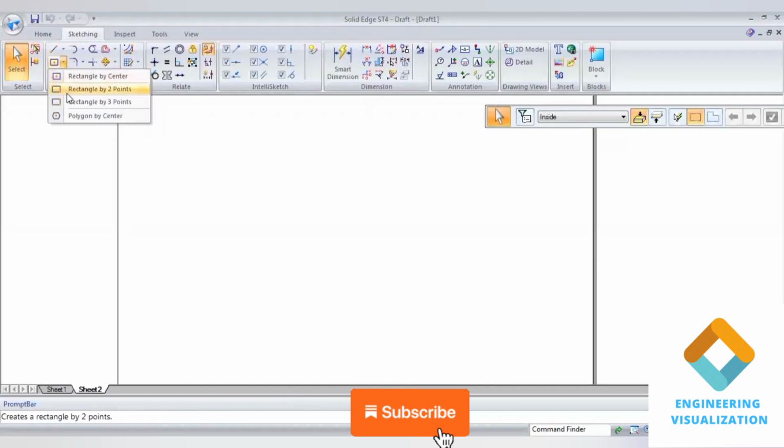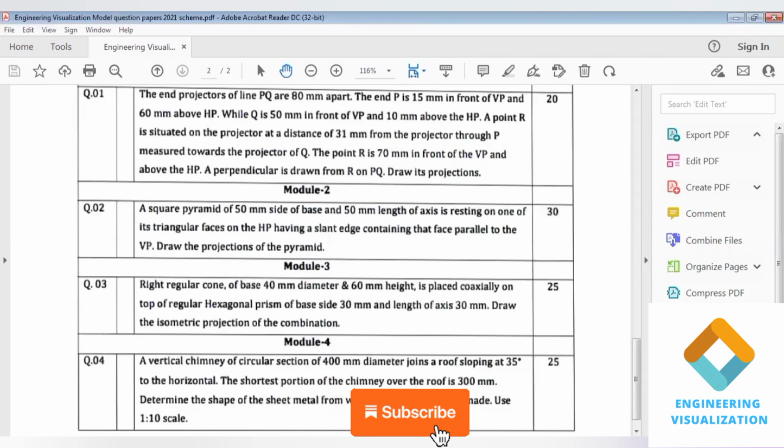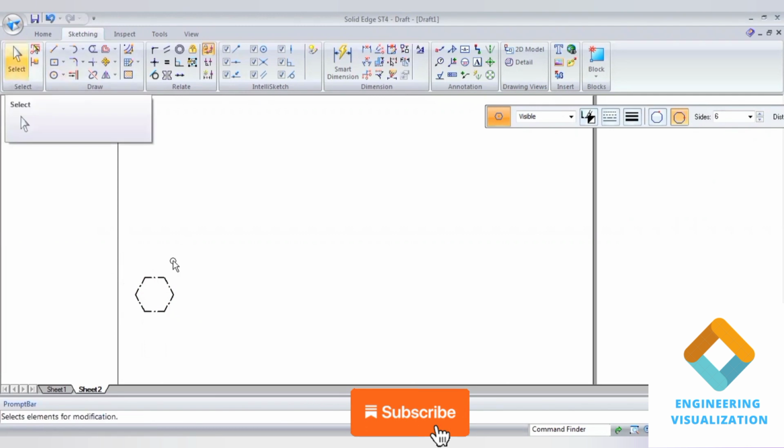That means first I should construct this hexagon. That is, first I have to draw the orthographic top view. So remember, for polygons such as triangle, pentagon and hexagon, we should always construct the orthographic top view, because you require box dimensions in order to construct it.